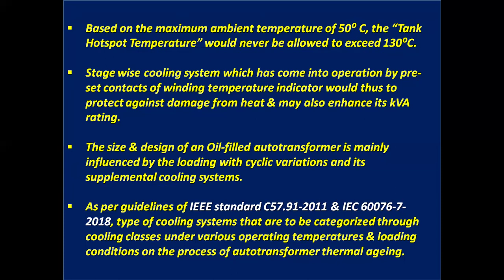Stage-wise cooling system, which has come into operation by preset contacts of winding temperature indicator, would thus protect against damage from heat and may also enhance its KVA rating. The size and design of an oil-filled autotransformer is mainly influenced by the loading with cyclic variations and its supplemental cooling systems.